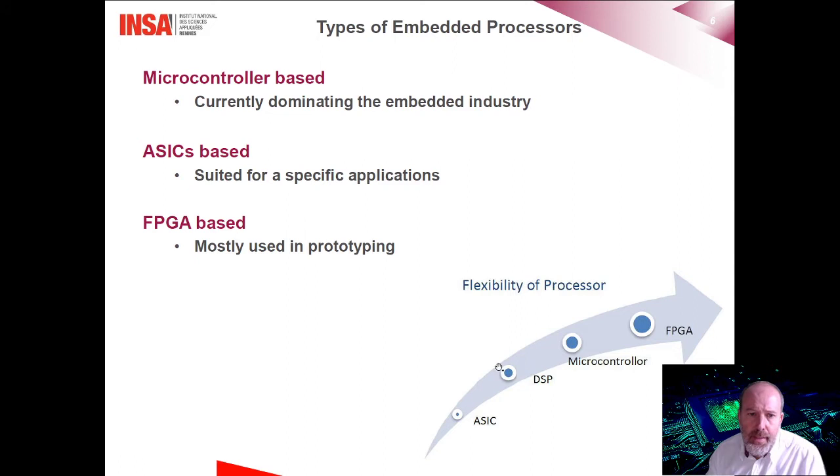Microcontrollers, which can execute several types of applications, are more flexible, but with less performance than an ASIC circuit. Finally, the FPGAs are very flexible since they can be reconfigured even during runtime, but will also have the least performance because the clock rates are usually low compared to their counterparts.